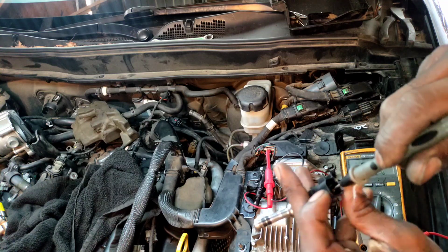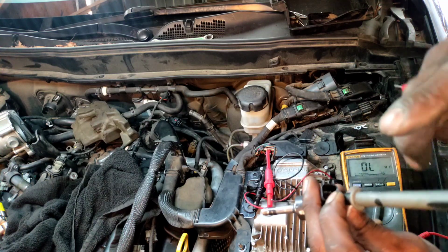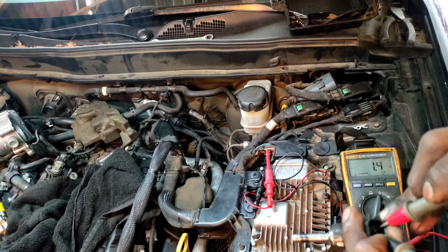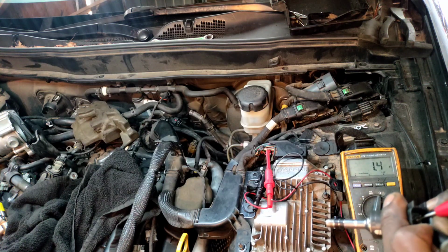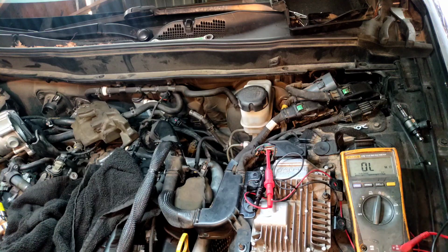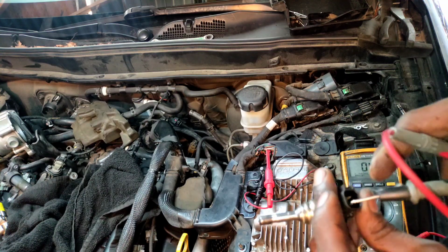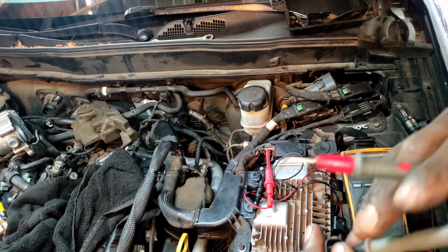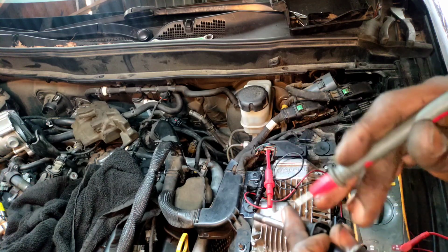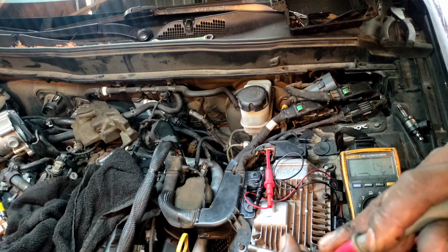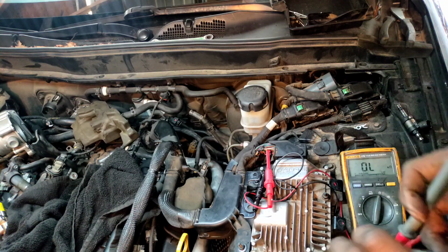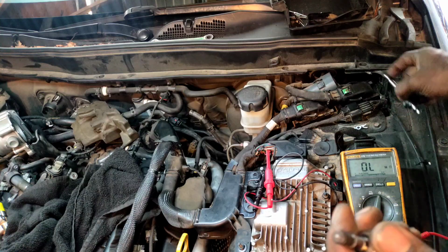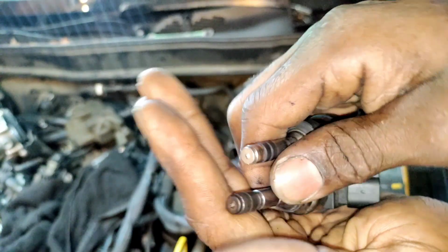I'm gonna do the exact same on the other one, put the ground lead on the bottom. So we currently got 1.4 ohms on the new one. I did the same test on the old one because they're about the same temperature now, and I literally had the same value, 1.4 ohms. So, I know resistance tests aren't that great, so we'll see what happens. Let's look at the tips here.